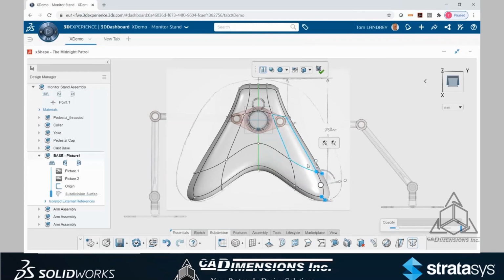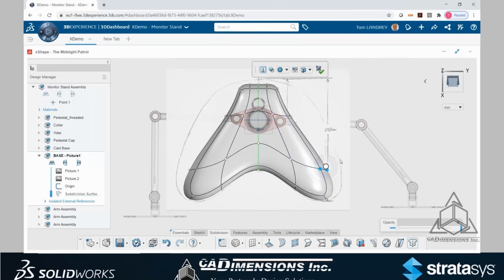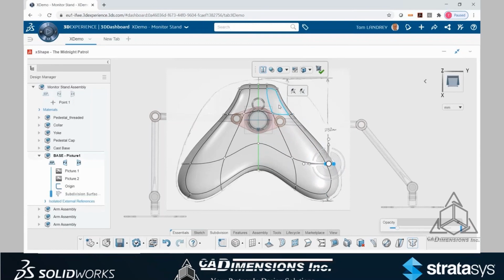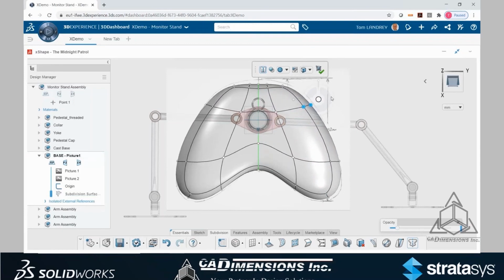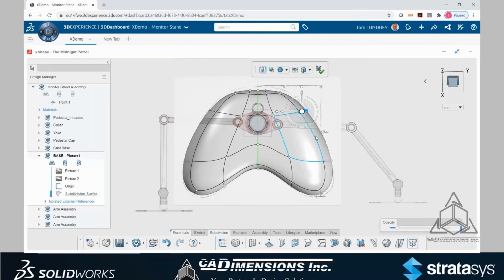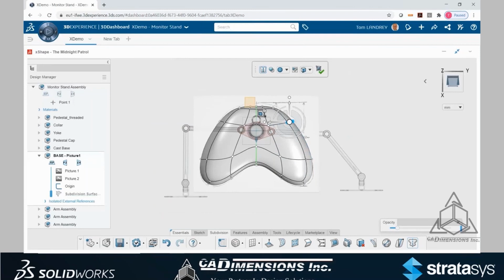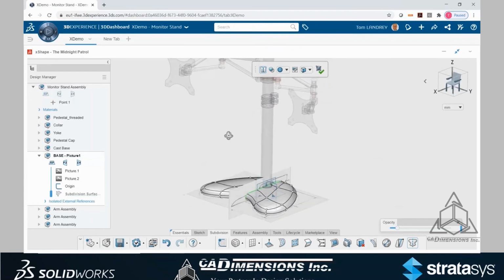So I'm pulling. Watch the pins that I just pulled, they're going to move a little bit too. Notice I'm not quite pulling exactly where I want to go, because I know the next work is going to go there. Now I'm going real fast. As you can see, this is an iterative process. I should be going around this part probably one or two more times just to get refined. I'm going to pay the price for that later, and I'll show you how I get around that. So here's a quick way to get pretty close to the shape. There we go. So that's from the top view.